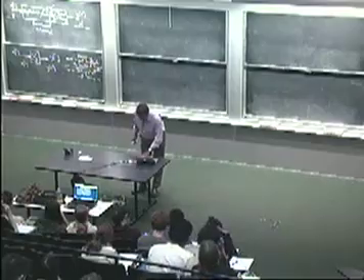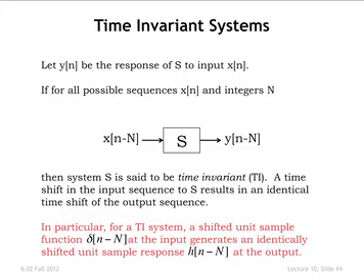Okay. And then we were going to specialize actually to the case of linear and time invariant systems. So I wanted to first introduce the notion of time invariance. Time invariance says basically that if you shift the input by a certain amount, then the output gets just shifted by the same amount, but the same input-output pair works as before. So what you're really trying to get at is a time invariant system is one where the laws by which you compose the values of the input to get the output don't change with time.